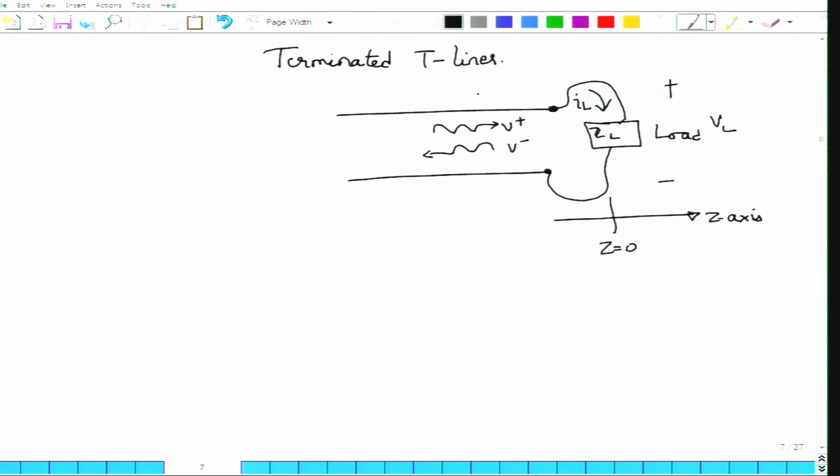Now, on the transmission line at any z that I can take off at any point on the transmission line, there will be both positive and negative going voltages, right. So, the total voltage here in terms of the phasor that I would have is given by V0+ e^(-jβz) + V0- e^(jβz). So, the V0+ wave or the positive z travelling wave will be going along the plus z direction, and this V0- e^(jβz) will be going along minus z direction.